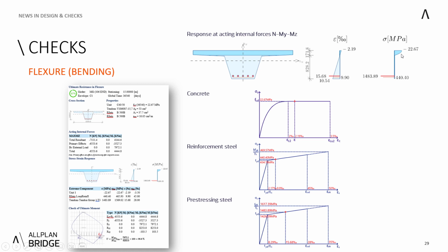Also, what can be seen here in the picture is that the tensile strains in the concrete are omitted for the stress calculation. So the calculation is nonlinear in material considerations. And therefore, all those tensile stresses are recovered by the rebars and the tendons. And as you can see both, they are using these inclined branches, so they don't use these unlimited horizontal branches. And therefore, after the yield stress, it goes upwards.